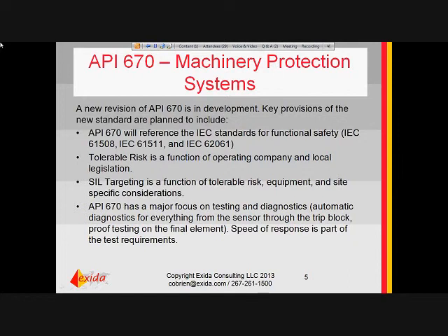It will also make a major focus on testing and diagnostics, trying to achieve as much automatic diagnostics as possible through the entire protective functions, from sensing through the logic solver to the final elements, and document the speed of response as part of one of the requirements. So this, I think, will provide quite a bit of information and guidance to further clarify some of the questions that come up when people are applying the functional safety standards to turbines.